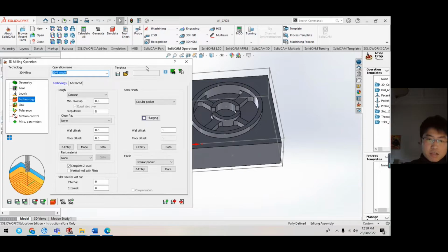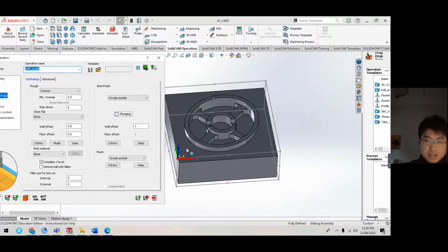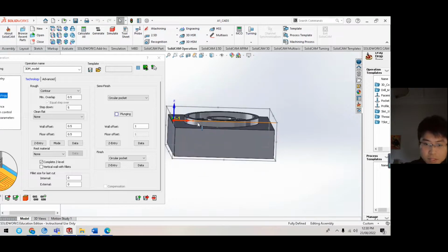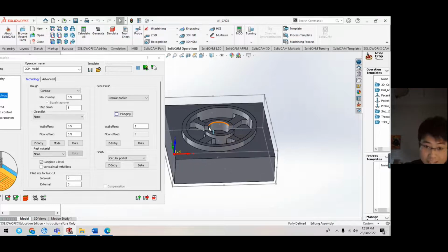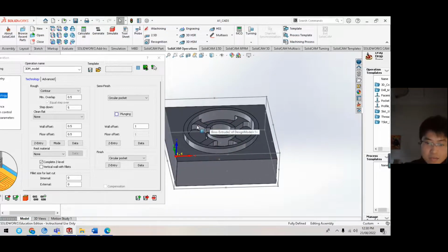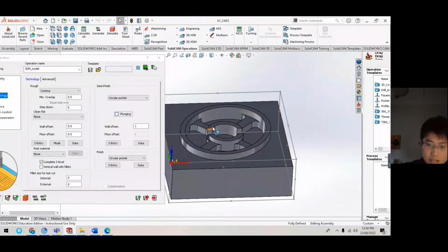For this 3D milling, we aim to cut the depth of the feature until like this on the outside, this circular part. We will cut this one up to this step, and also for the inside, we will cut up to the top of this circle. And very luckily, the depth from here and from here will be the same. Therefore, we can conduct this operation together.